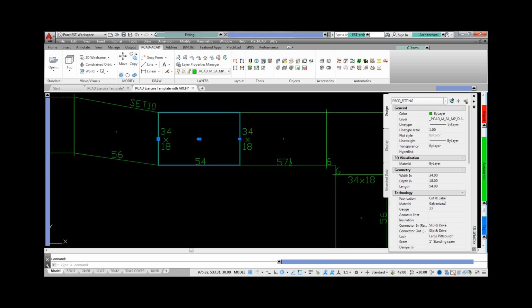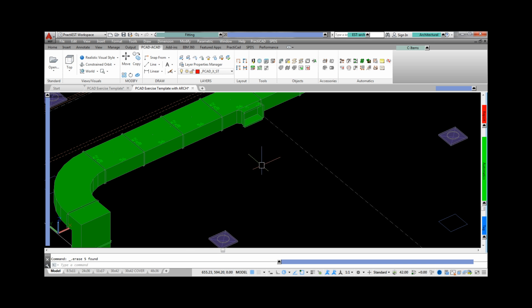Following that, we will change the connections, and you can see it's adjusting connectors of surrounding fittings and also adjusting length. If we bring everything back to what should be a coil line piece, PractiCAD will automatically update it again. By specifying your criteria for what fitting should go to what machine, we can completely automate the download to PractiCAM. So let's cover the workflow for drawing duct again.